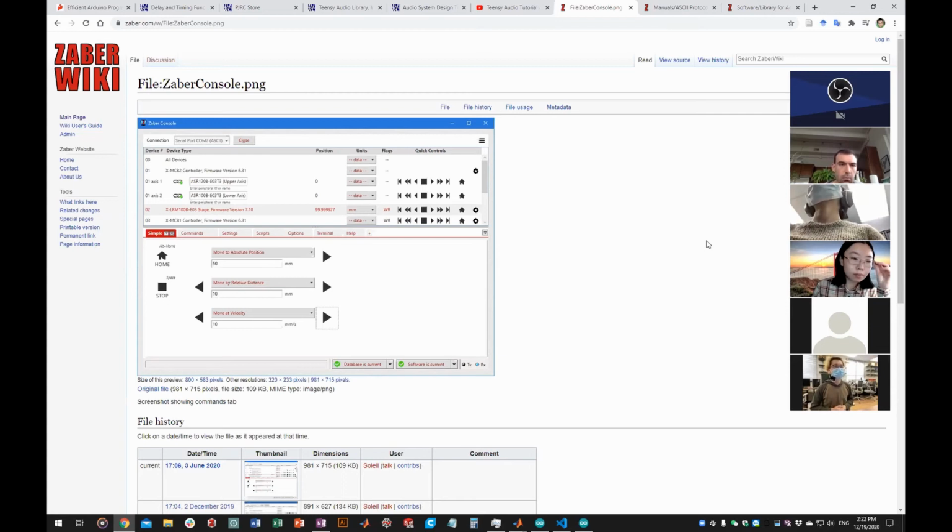controlling channels. To configure that, you need to download the Zaber Console software, connect your controller to your computer, and let the console recognize that controller, and at the same time connect your stages to the controller. There's a place that allows you to specify what stages you are using, and try to be very specific to the models, because different revisions of the same stage may have different currents and different sorts of specs. So just make sure you configure that.